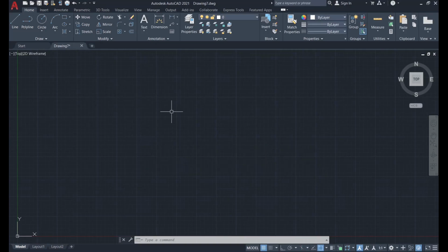The most important settings in AutoCAD are the units. So you have to set the units in millimeters, inches, or what you prefer. But do that before you start any drawing, because later on it's tricky to change them and AutoCAD will not acknowledge that change every time.